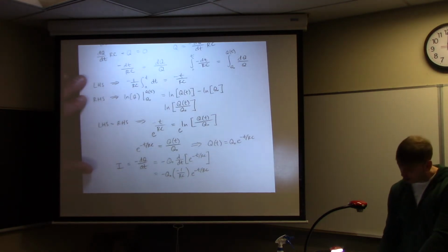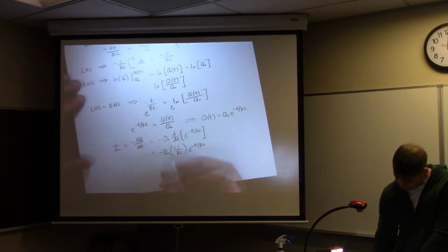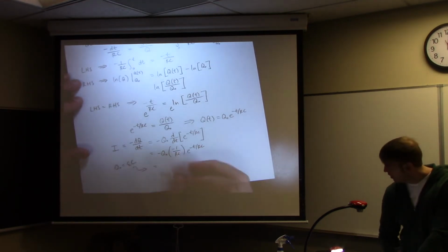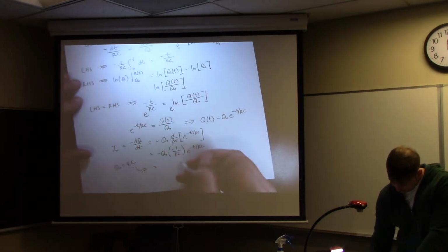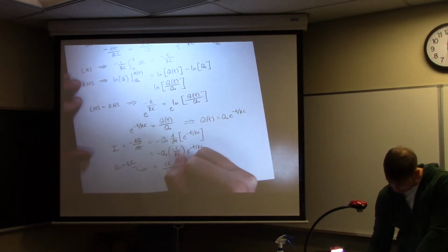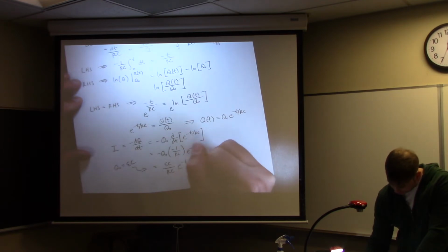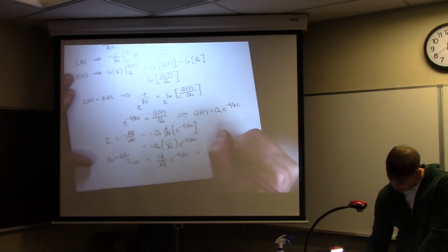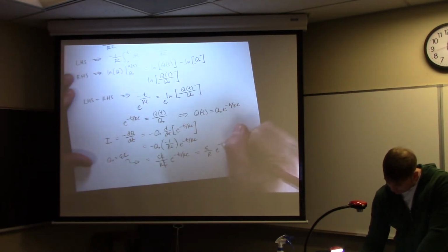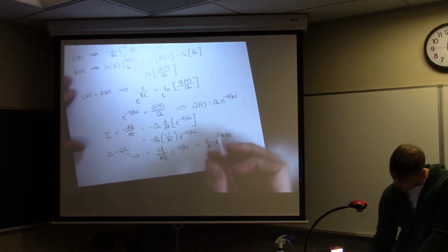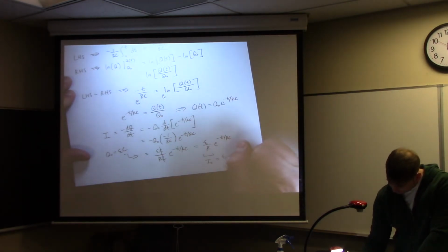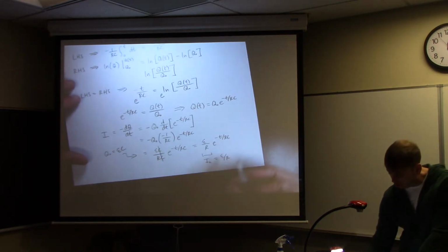And of course, that gives us the current. But remember, from before, when we see Q naught, we're talking about the maximum charge, which is epsilon times C. So cancel out the two negatives. On top, we have epsilon times C. On the bottom, we have RC. E to the minus t over RC. Cancel out the C factors. What do we have? Epsilon over R, e to the minus t over RC. And then just remember that this is our maximum current. The maximum current is epsilon over R.